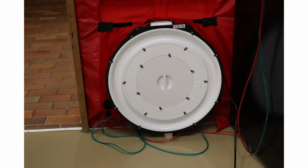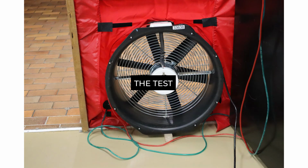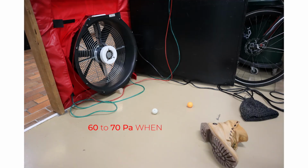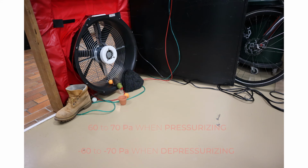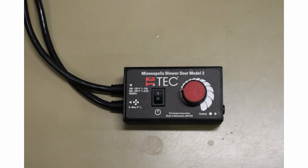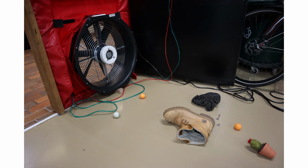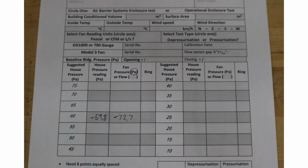The rings of the fan are then removed from the fan and the fan can be started. Most tests require the building pressure to be increased to 60 or 70 pascals when pressurizing and -60 to -70 pascals when depressurizing. The fan speed can be increased using the dial until the manometer measures the building pressure recorded on side A. The pressure across the fan is measured at the specific building pressure over a 10-second average.